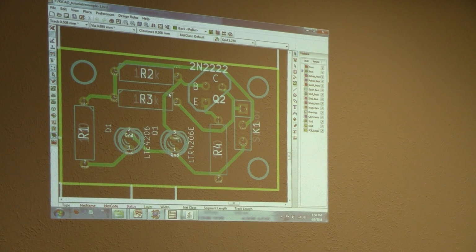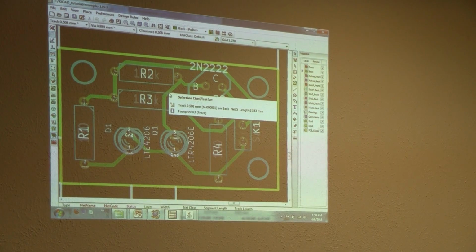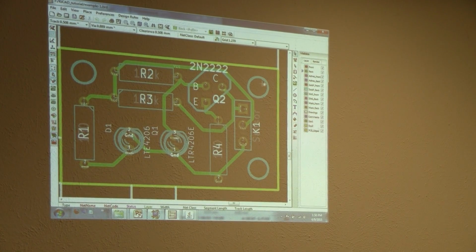All right, so I got a PC board. One of the things that after I've done the auto routing, I would often go in and put a via in the middle of these on the back side of the copper, so that when I drilled the PC board, it would be easier to drill, because those won't show up as any copper. These are just on the top side, there for me to know where they are, so I wouldn't put components on top of them.